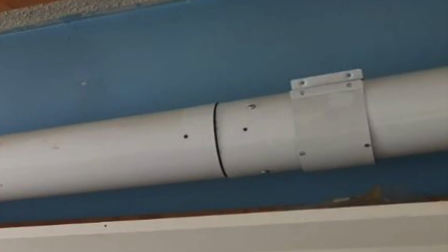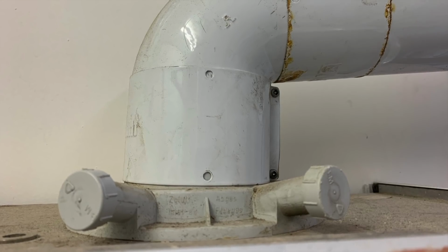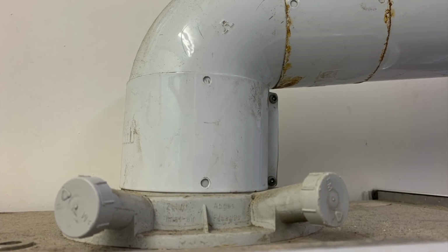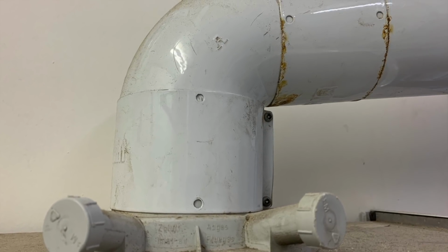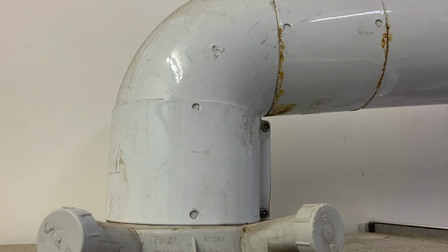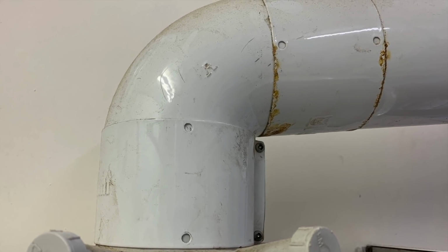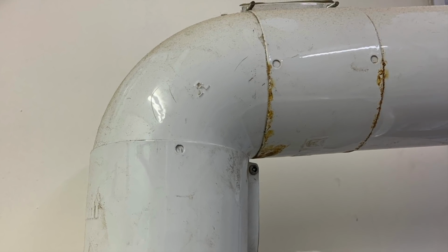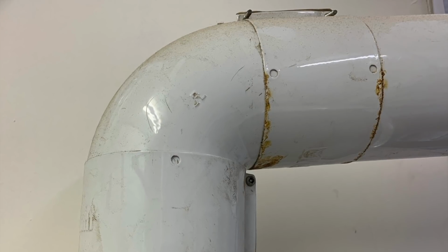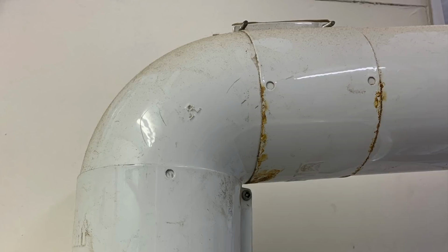So if we have a look at this other Vaillant flue system, you can see first of all that the collar is too big where it joins the flue elbow to the turret, and it's not screwed. And the other collar shows signs of corrosion and isn't screwed also. So this is showing signs that the seal has gone, and this flue again will be classed as at risk, and if you were getting products of combustion coming into the room, it would then be ID.